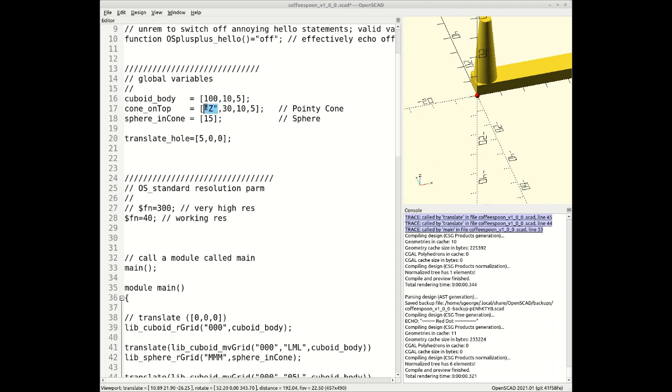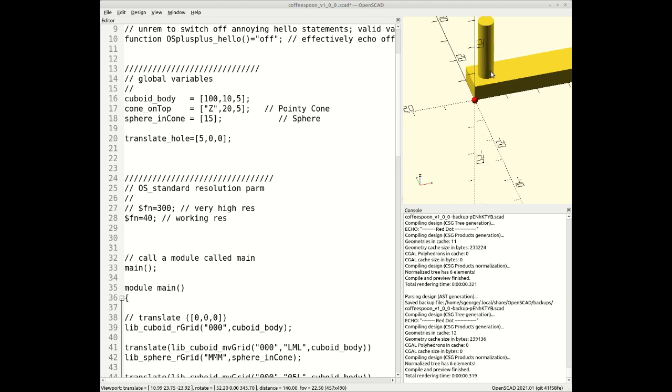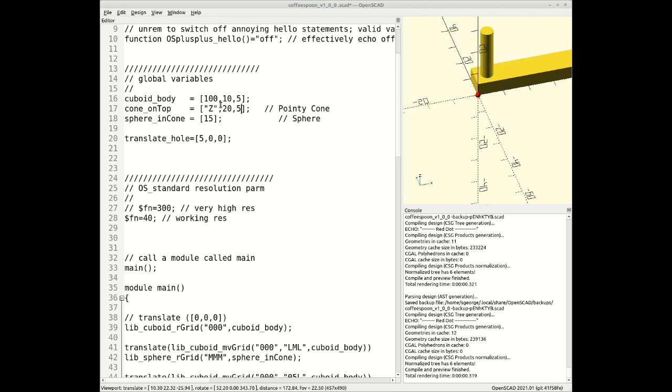Right, that's the strangest hole I'm going to need. So the Z's in the right direction. Let's make the thickness 20, and I want a hole of, let's say, 5. There you go. So there's my cylinder pointing up in the Z direction. It's got a length of 20, and it's got a roundness of 5. Let's make it 6. Why not? Okay, F5 to make sure it all works.